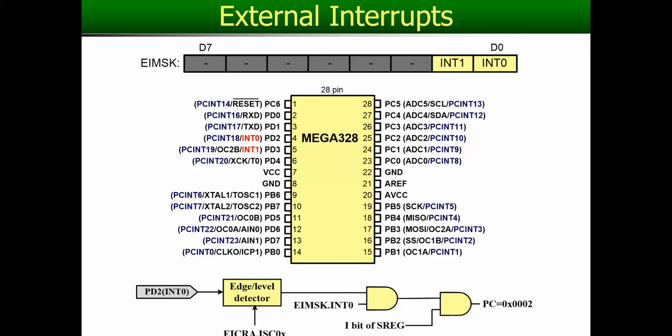That means that nothing has happened by mistake. The programmer knows what he's doing. He has enabled the global interrupt feature, and he has also exclusively enabled the external interrupt 0. Okay, and then whatever line of code the CPU was executing, let's say it was at line number 000E or 005F, whatever.